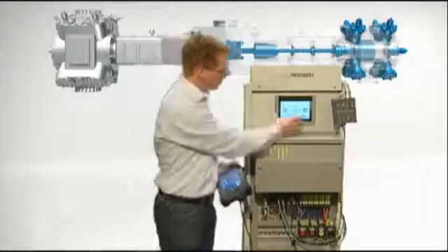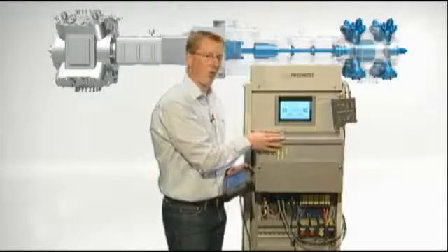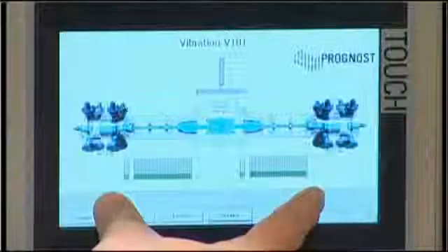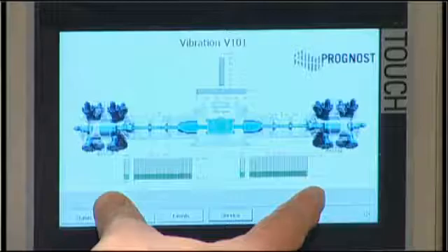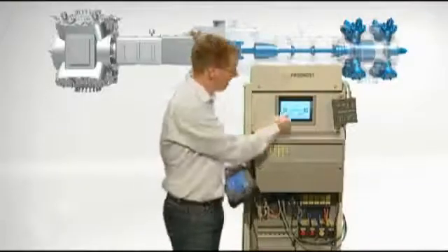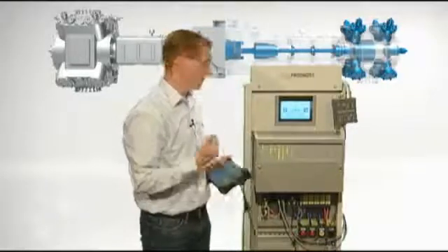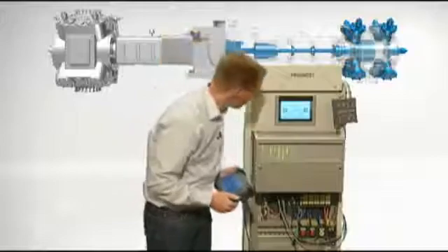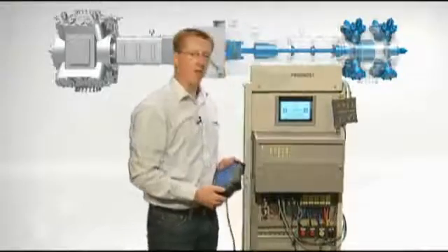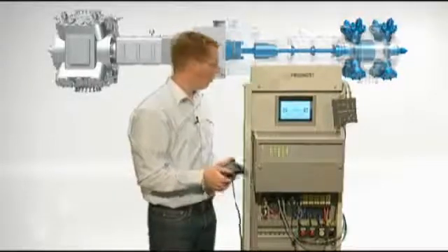On top, we see that in this application, this protection rack monitors a 2-throw reciprocating compressor, which is safeguarded through 2 crosshead vibration sensors, acceleration sensors, ICP type in this case, and we also see the corresponding speed indication. That machine runs at 300 RPM right now, smoothly running. Currently, we monitor about 5G, 50 meter per square second of crosshead acceleration per throw.